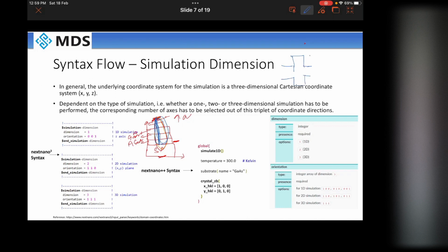In between you have GaN, then AlGaN, then again GaN. So your structure will be like this, and once you apply the bias condition, this will tilt down, and because of the electric field, the electrons can travel through the barriers. So if you draw a 1D plot, that is good enough to characterize the device. But now I'll take the case of a MOS transistor.